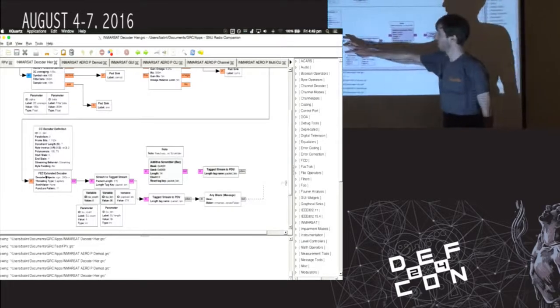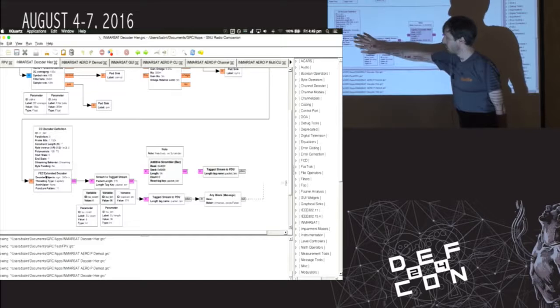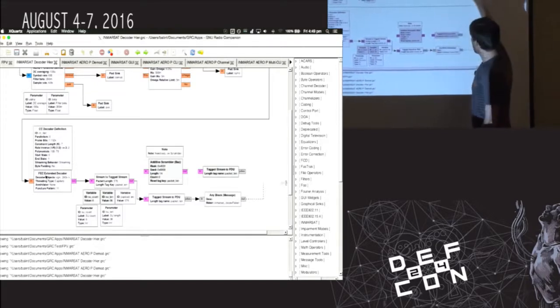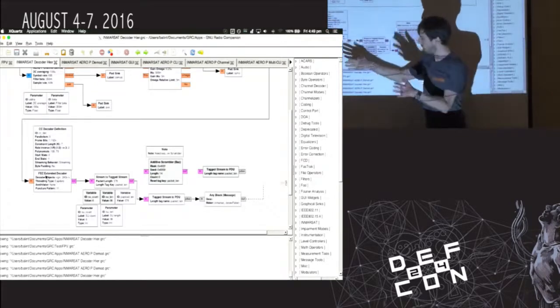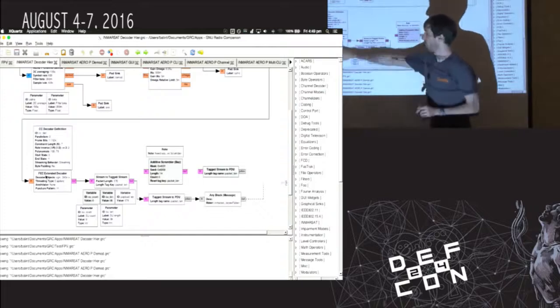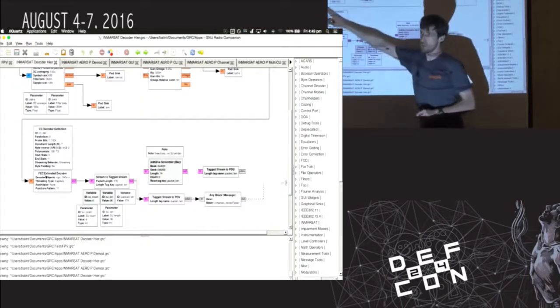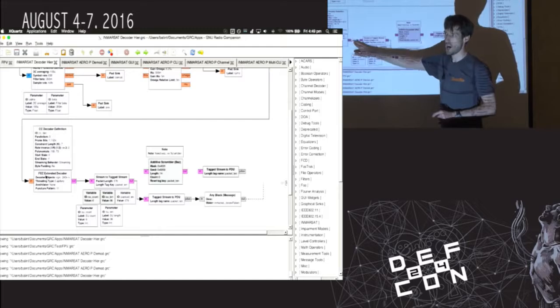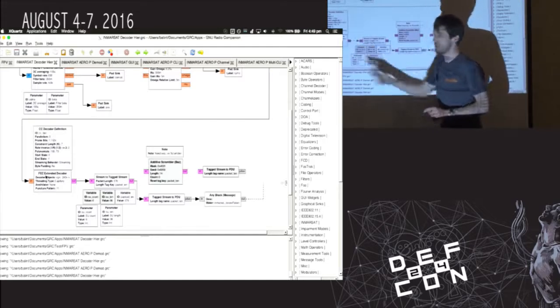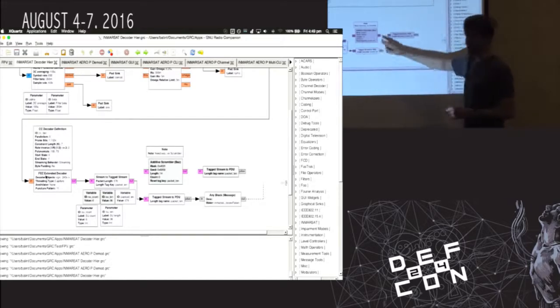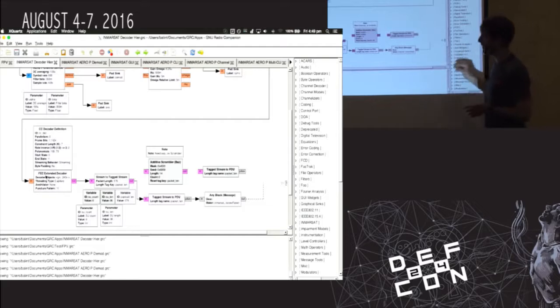So this is what's implementing that convolutional decoding. It's passed an entire payload's worth, and then it decodes that payload. And then these are soft bits coming in, and then it puts hard bits out. So it uses those soft bits when traversing that trellis to find the most likely path.